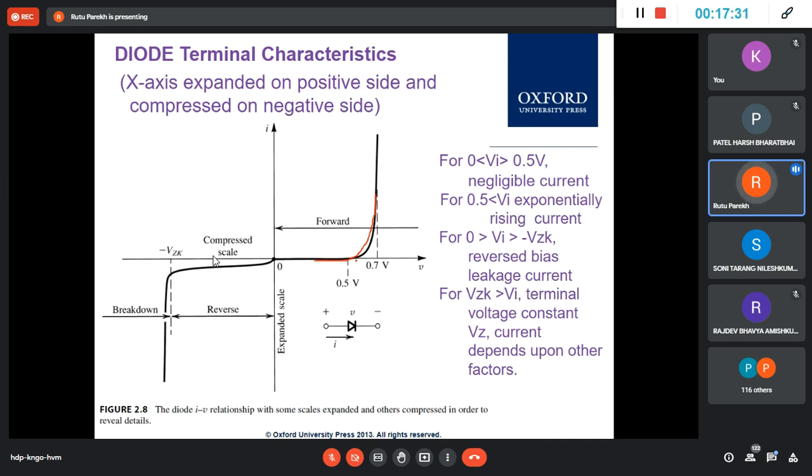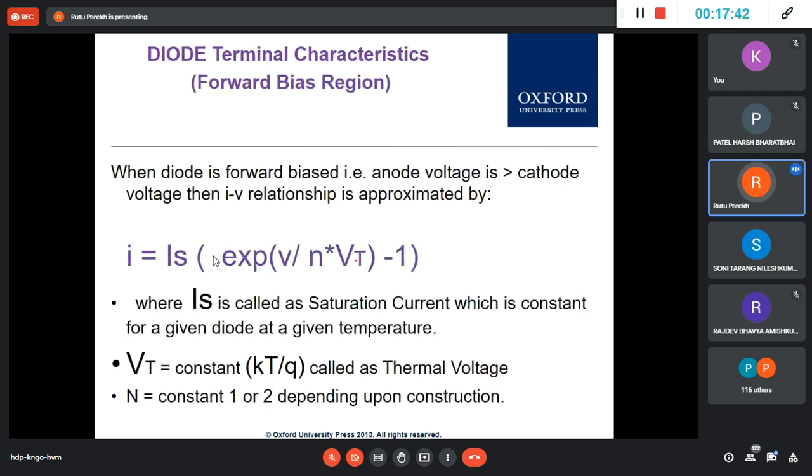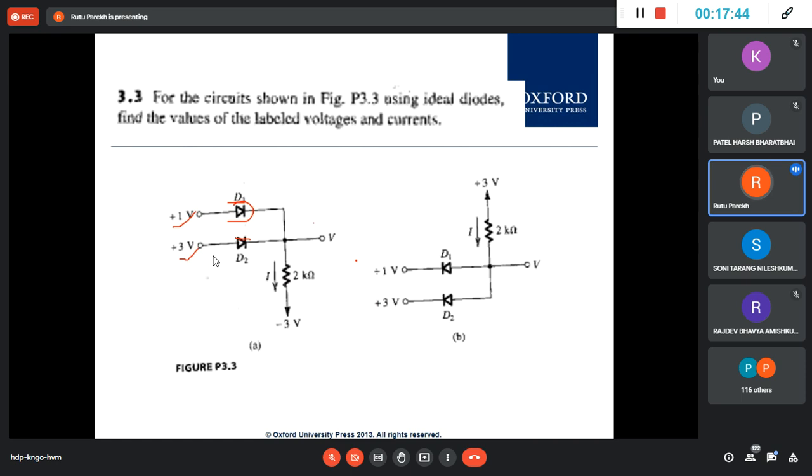So the +3 volt one, in you know microseconds, or milliseconds, a thousandth part of a second, it will start conducting little earlier because it is getting more voltage. If you talk in terms of IV curve, this will start conducting, you know, in some microseconds little earlier than this guy.